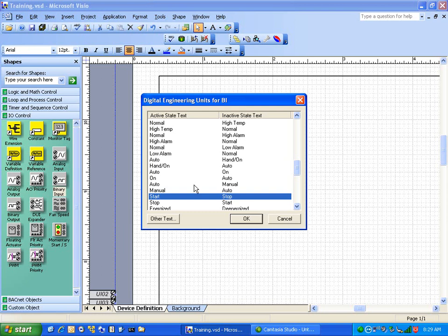If it comes to something like a variable speed drive, I'll use more of an output, labeled enable, disable, or if it's a boiler, enable, disable. That's the only twist I'll have on a pump. If we're enabling a drive, I like to label it just as we're doing it. We're enabling the drive, and the drive, with all the safeties tied in, is going to start the pump. Or sometimes I do simply use start stop for a drive as well. I guess it really depends on the mood I'm in that day.